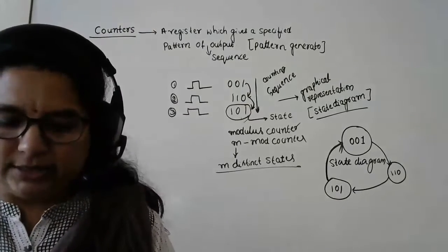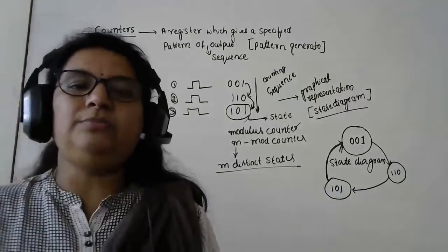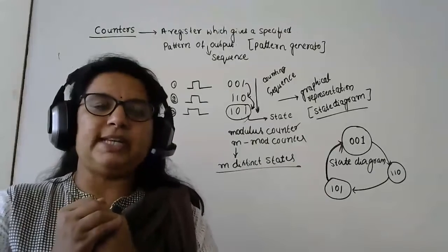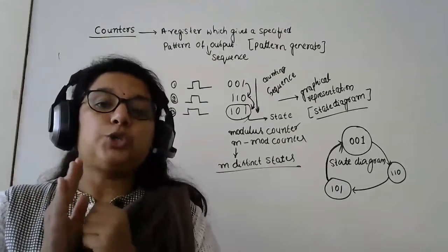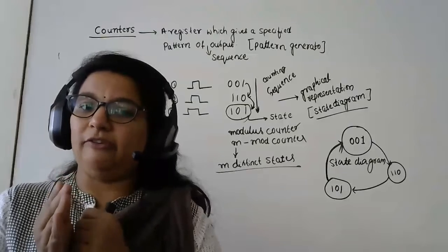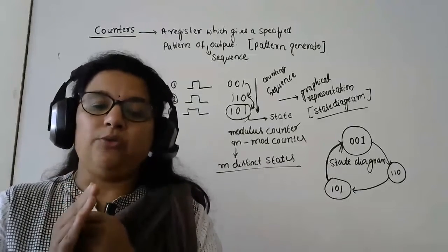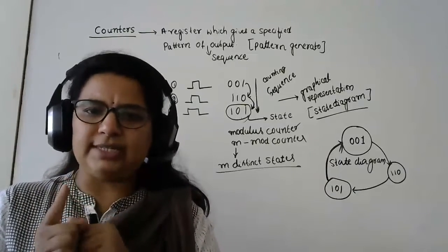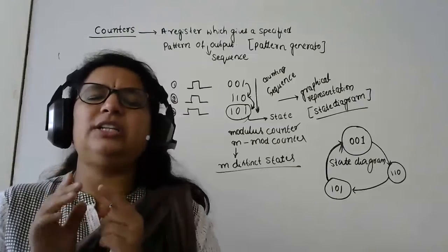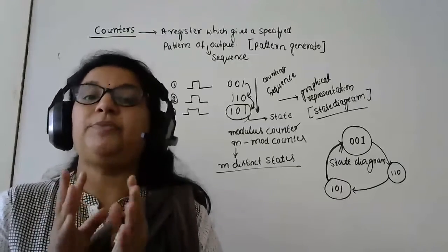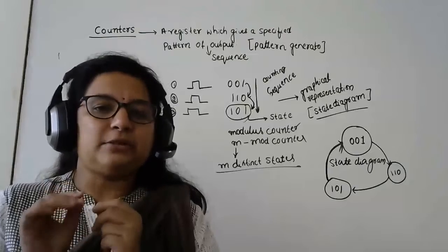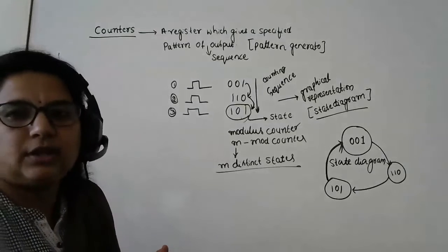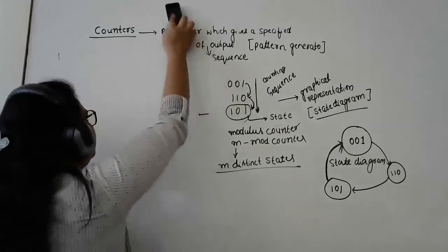Okay. So now let us look into how to go for a counter. See, till now we were talking about the shift registers, which are used basically for holding the data or moving the data, right? So in that case, the type of flip-flop I have used was a D flip-flop. Now, whenever we use registers in the form of a counter, the one significant change is that instead of a D register, in counters you will usually make use of T registers, toggle registers. Why? Because that helps me give a specific pattern of output. Okay, so now let us take an example of one binary ripple counter.